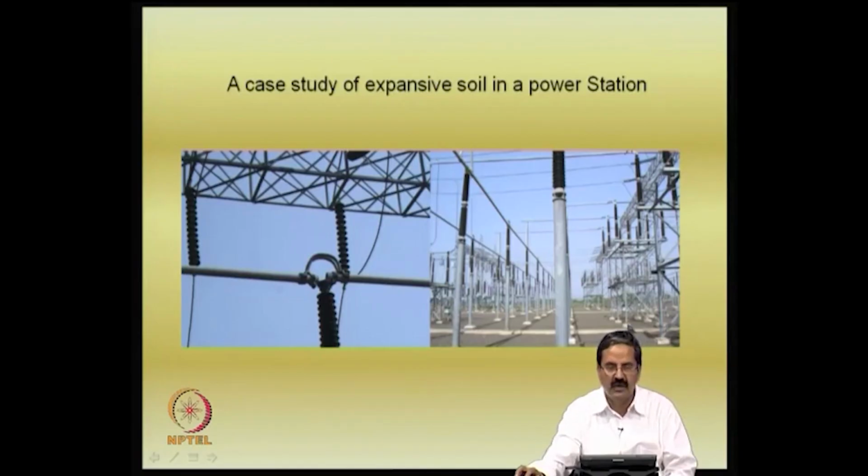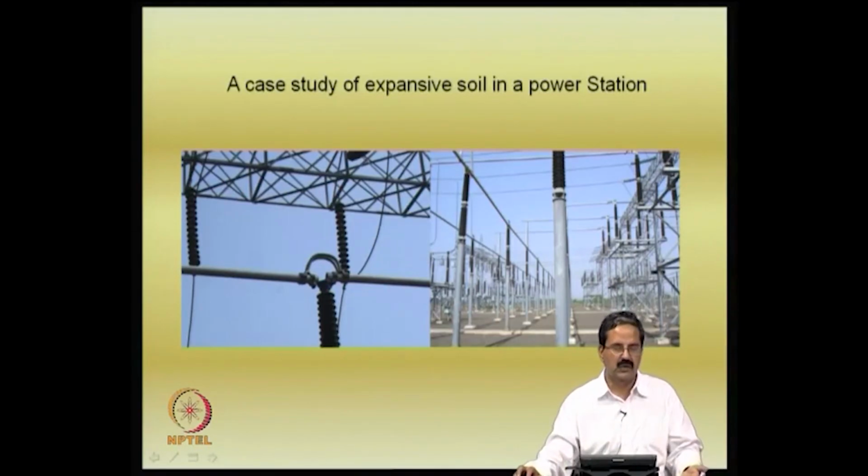They will have a minimum foundation which could be about 1.2 meters or some 2 meters depending on the junctions, loads coming on that. They have lightly loaded structures, the load that comes on this is much lower compared to the swell pressure. In fact, the expansive soil in this area has a lot of swell pressure, it could be about 150 kPa and all that. The load that is coming here is so low that definitely you expect during the heaving and